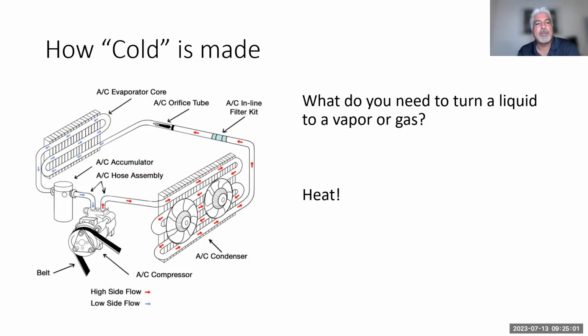But before they started the flushing event, they actually weighed every component, from the evaporator to the lines to the compressor to the condenser. After the flush, and they did it per the instructions, everything weighed more, which said that there were still remnants of that flushing agent in the system. In other words, you can't get it out. So the consensus was, should we be using a flushing agent?